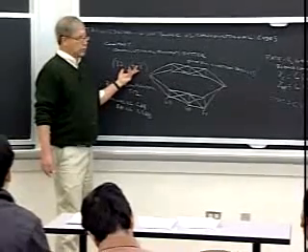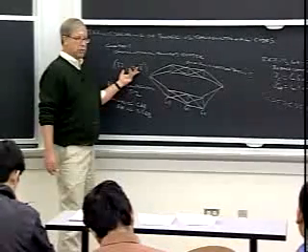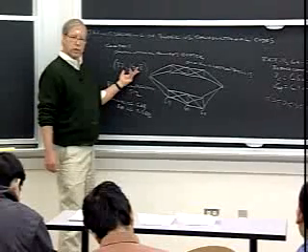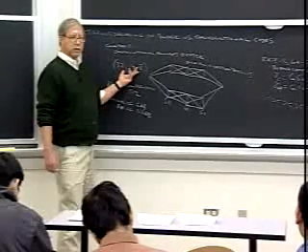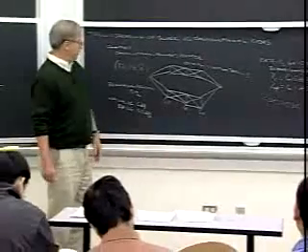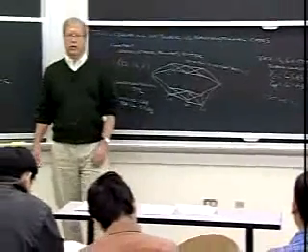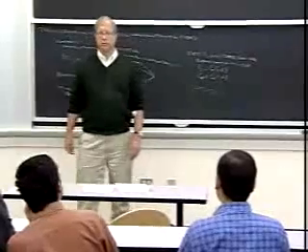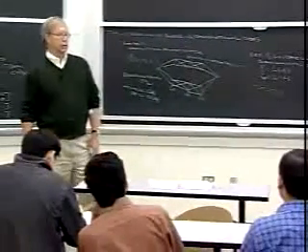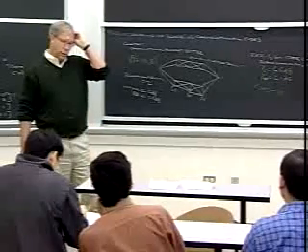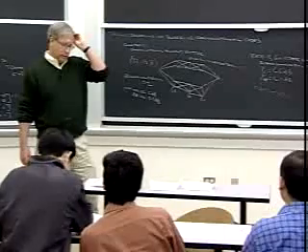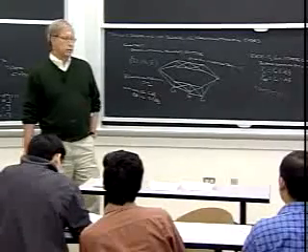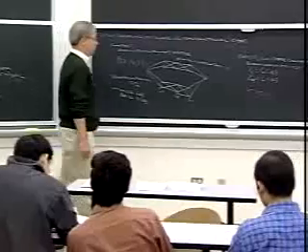So for short block codes of length less than 100, or let's say 128, the best we know of right now is to pick a good Reed-Muller code or BCH code, find its best trellis, and do maximum likelihood decoding. It used to be that you thought of 64 states as a lot of states. But clearly technology has progressed, and now you wouldn't blink at 1,000 states, or maybe even 8,000 or 16,000 states. The biggest Viterbi decoder that was ever built had 2 to the 14th states for the space program out of JPL. So anyway, it's doable now.